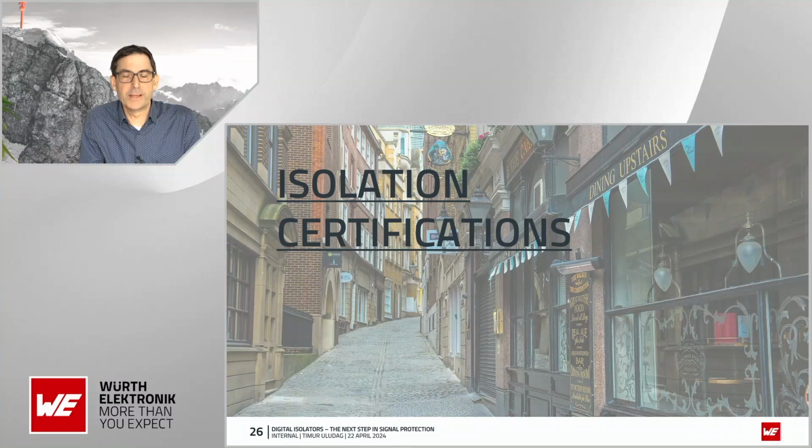So now we know why, we know how we can implement, we know how the digital isolator is built up, but in an emergency, the digital isolator should protect, should be a shield between dangerous, hazardous voltages and the person.